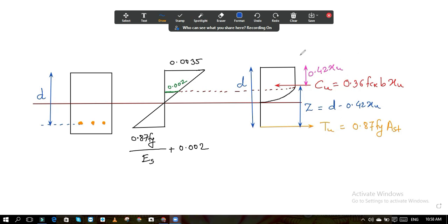You know that for the doubly reinforced section, what will be the change? Here we provide the compression reinforcement. Then two forces are there: first is Cu1, second is Cu2. Cu2 will act at a distance of d dash, where d dash is the cover in compression. Where we show the reinforcement, we left some cover from the top. The distance between Tu and Cu2 is d minus d dash, that is the lever arm. This also we have seen in DCS. So this information I have given to you just to recollect and rebrush.